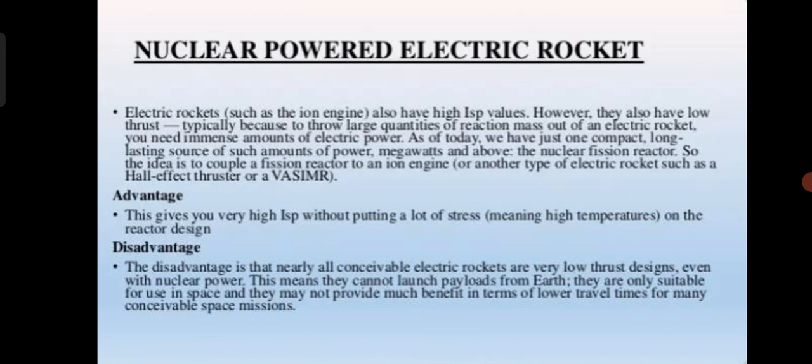Advantages: this gives you very high ISP without putting a lot of stress on the reactor design. Disadvantages: nearly all conceivable electric rockets are very low thrust designs, even with nuclear power. This means they cannot launch a payload from the Earth. They are only suitable for in-space missions.